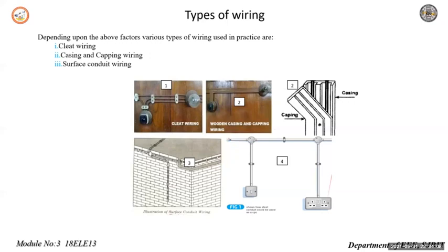The standard length of conduit is generally 4 meters. The conduits are threaded at both ends with one coupler attached. Based on the outer diameter, various sizes of conduits from 12 mm to 63 mm are available. The conduits are supplied with a black enamel coating on the internal and external surfaces. The conduits are to be erected completely before laying any cable in them.